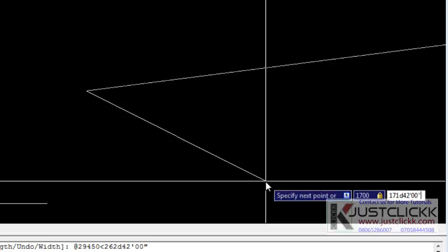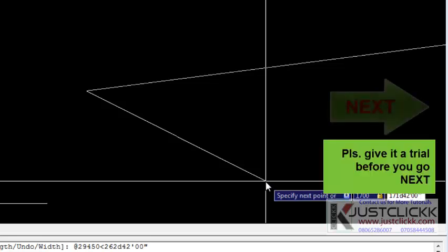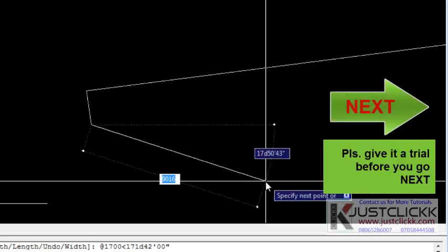So you see, this is how you will continuously be entering the coordinates. You enter the distance, you enter the angle, you press the enter key, and you're there. So by the time you continue this way, it will take you round back to the starting point, which gives you the coverage area of your site plan. So let's go ahead, press the enter key. I've gotten the result.